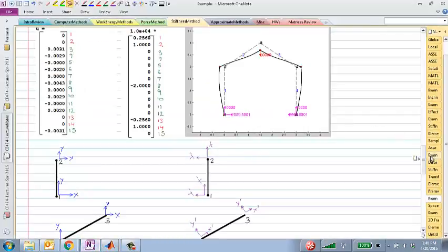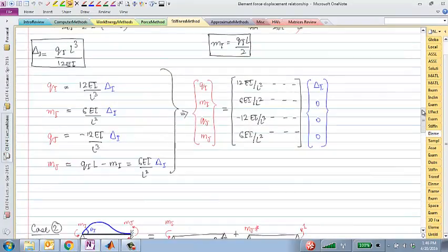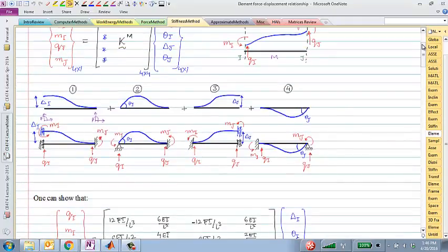You remember when we derived the beam stiffness matrices, we had these 4 different shapes. These are the 4 different shapes that are used to plot along the length of the element. Each beam element won't be a straight line. For truss elements, it's easier because even the deformed coordinates, the connectivity is just a straight line. But for beam elements, it's not a straight line. You need to take the precise shape of this deformed shape for different cases.